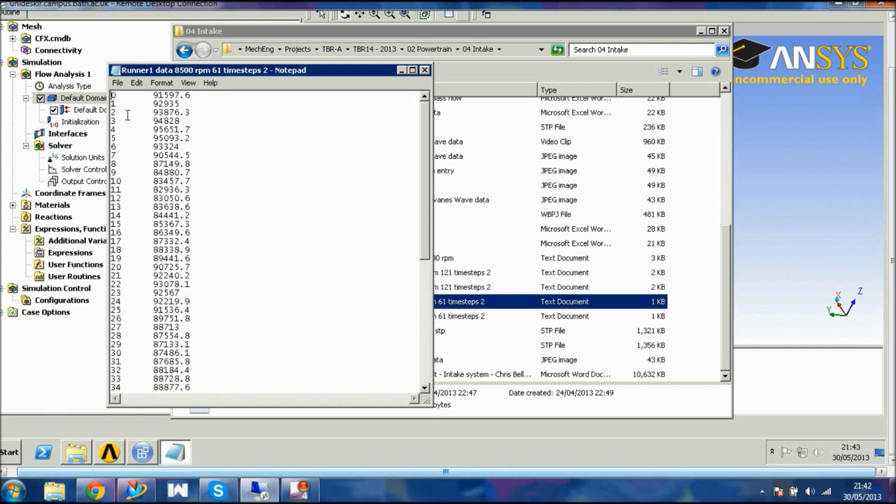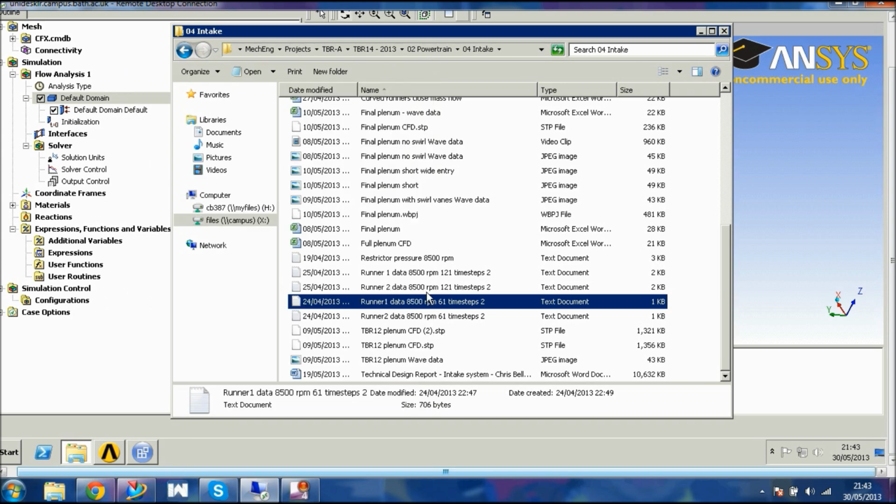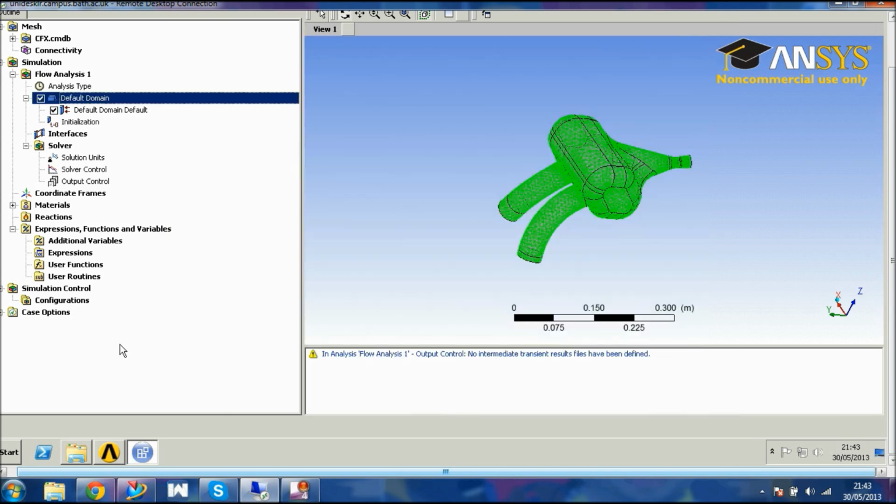And then in Excel you just save your Excel file as a text file, and it should produce something like this. This can then be read by the Ansys software, and read as a changing pressure for the time step. I've saved those 2 data sets on the X drive as well, in the same directory as the plenum step file.